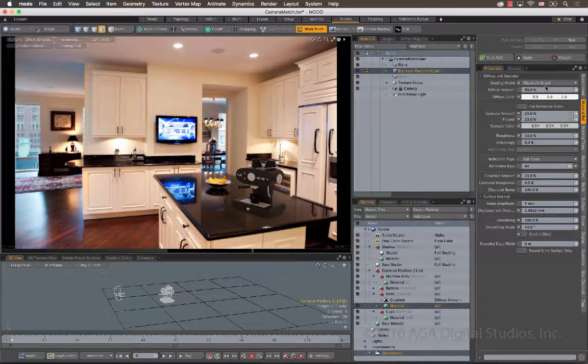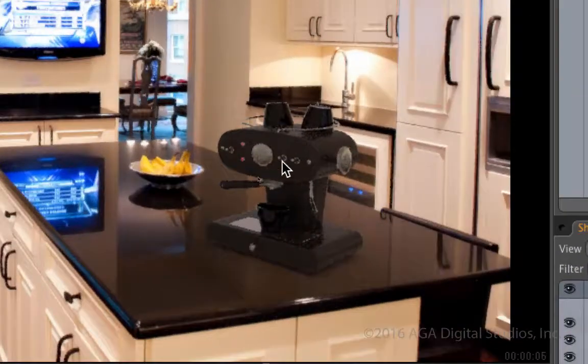And the way to make the metallic with this physically based is to have kind of a bright color for your diffuse, but then, or actually I should take that back, you should have a bit of a darker color for your diffuse and then a bit brighter color for your specular. And you get kind of a nice metal. Works pretty well. And if that's not bright enough, then you can increase the Fresnel and decrease or increase the specular, depending on how you want that to look. And the roughness, a higher roughness, of course, is rougher, and a lower roughness is a little bit smoother and shinier.